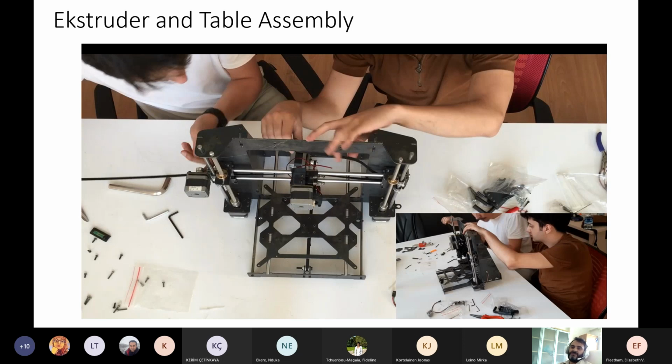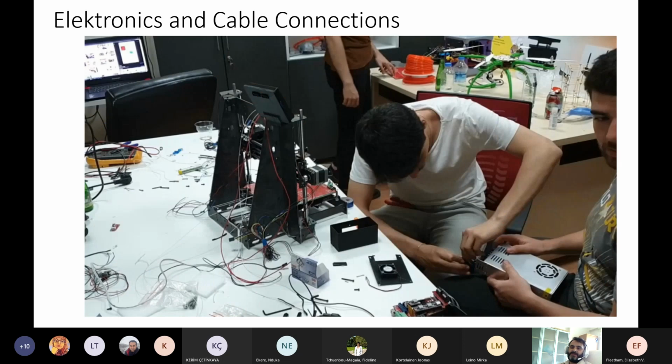So we have two guide shafts each for the X, Y, and Z axis. By the way, there are two worm gears for the Z axis. Essentially, these two worm gears and two guide shafts act like supports. So our Z axis is the best supported axis here, and hence it is the most stable and accurate axis we can expect.